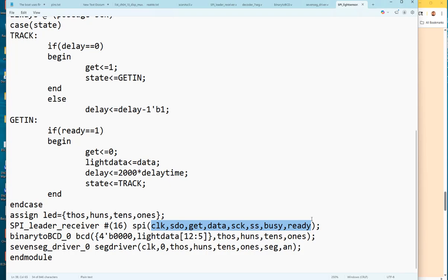And one of the questions in class 11, question number 7, asks about positional association. All right, the signal lines over here in the parentheses are the signals from where? From the sub module being instantiated, or from the top module? It's from the top, right? So that comes from the top. So when you look at these signals, actually when you code it up in the top, you write down all the top signals, and at the same time you open another window for the sub module to make certain connections to them, right?